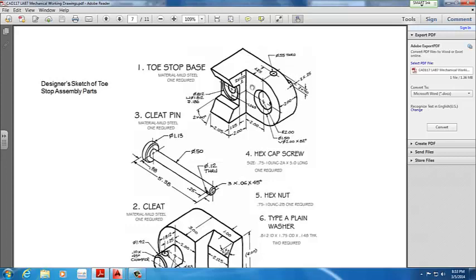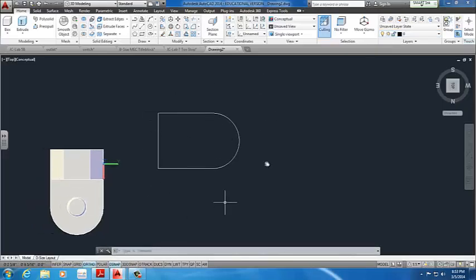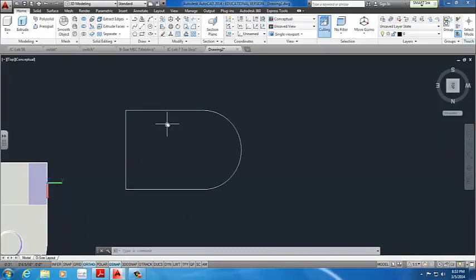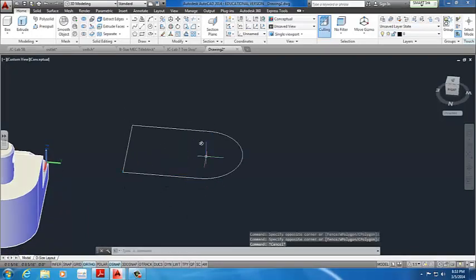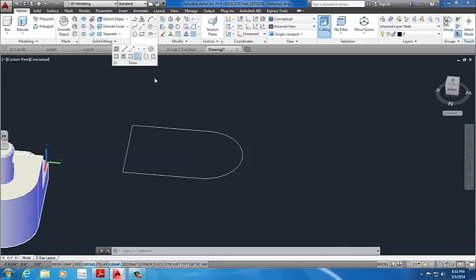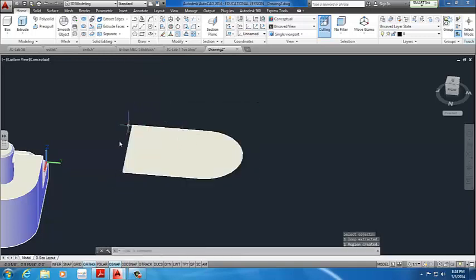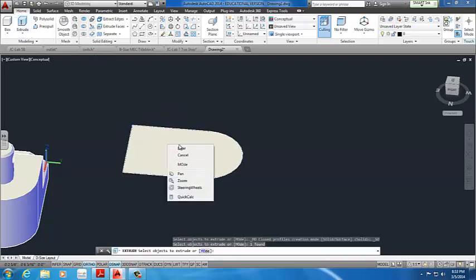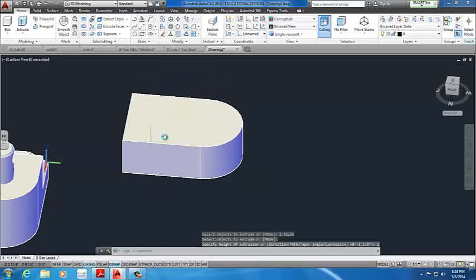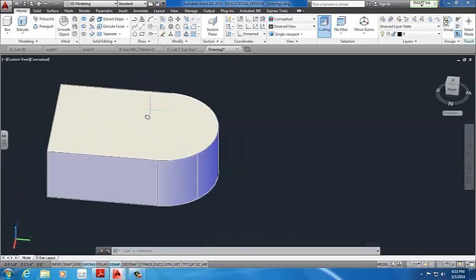But before we can actually start cutting this out, we have to extrude it out to make it a solid object. I recommend press pull because I won't have to put these lines together. But if you do not know press pull, or you can't have access to it because your older version of AutoCAD does not work, you have the other option of using region. So you go to draw, region, select the entire object. It will shade the object. At this point, you can select as is and extrude it out, which is going to be 2, giving you exactly what you need.